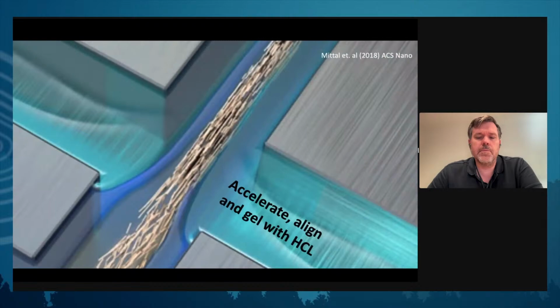In a second step, you align it more, you enhance the speed, you get an elongational flow, and you are then adding, in this case, a proton system, so an acid that diffuses protons into the gel string, which causes the gelling. So the idea is that we can lock the dispersion with aligned fibers, nanofibrils, and in that way get a strong final material. And that proves out to work.